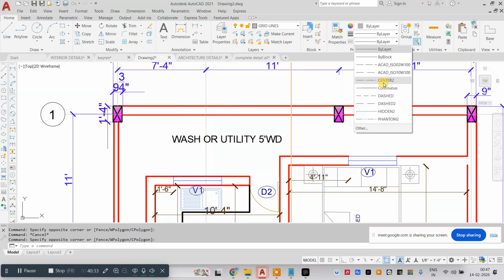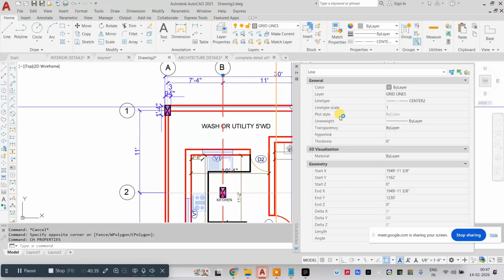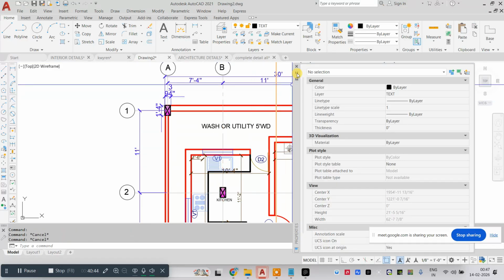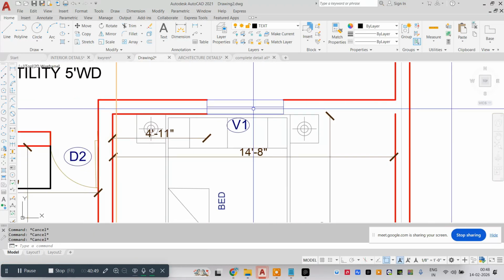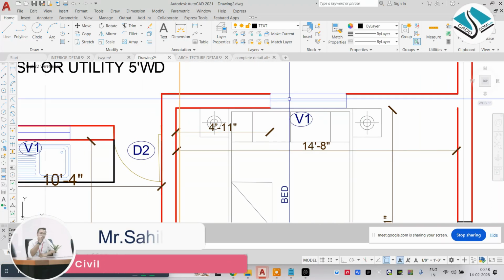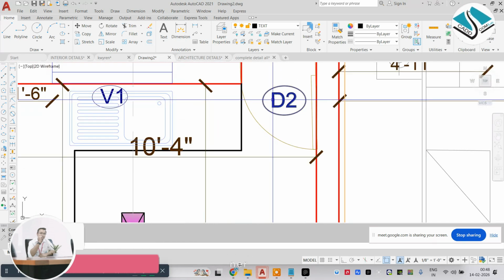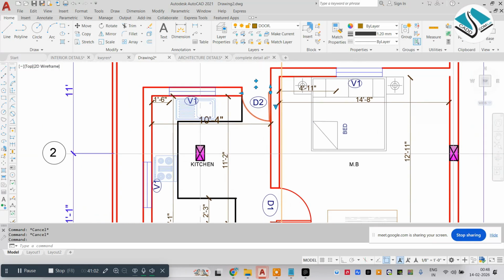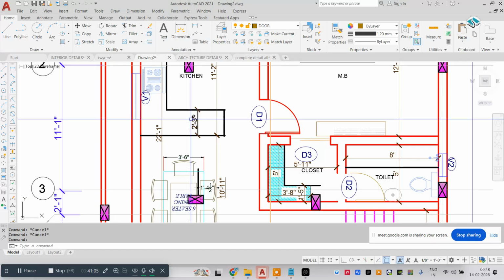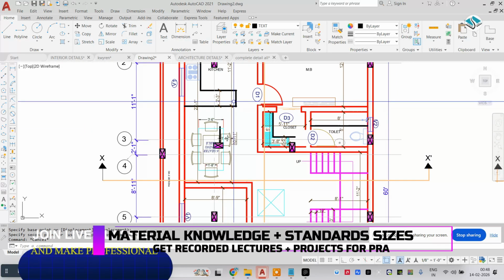Change your grid into a center line too. All grid lines should be on a specific line type. It's very important. Focus on the columns, finishes, door and window finishes, door tag and window tag. It's very important. That's why we say that basics should be clear before working on this kind of details, right?